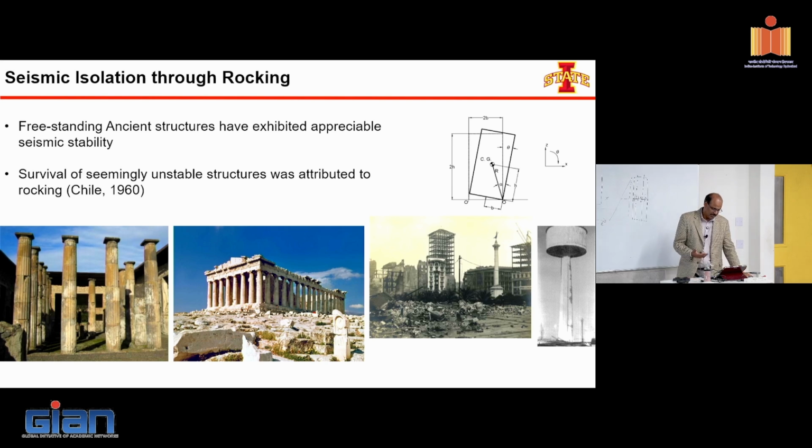The other thing I mentioned to you was that in cemeteries, they have these monuments. In the old days, they built tall monuments, and they didn't establish any connection. They put them on a large support, some kind of pad, and put it in place. And they found that in the earthquake region, not all of them fall down. Some of them survive, some of them don't. So that's when Hausner looked at what aspect ratio influences a free rocking response. That's how the whole thing started.